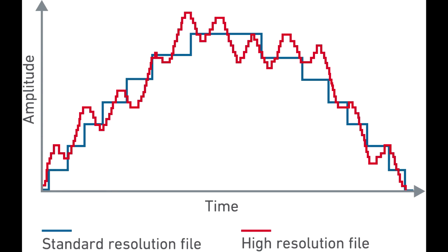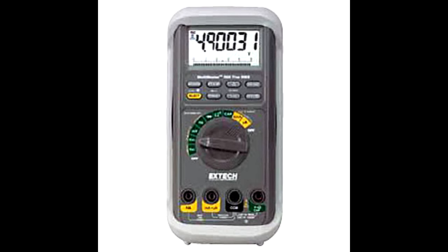Resolution is the ability of the measurement system to detect and faithfully indicate small changes in a characteristic of a measurement result. In other words, it is the degree in which change can be theoretically detected. When looking at a digital device like a multimeter, the resolution will be the least significant digit.